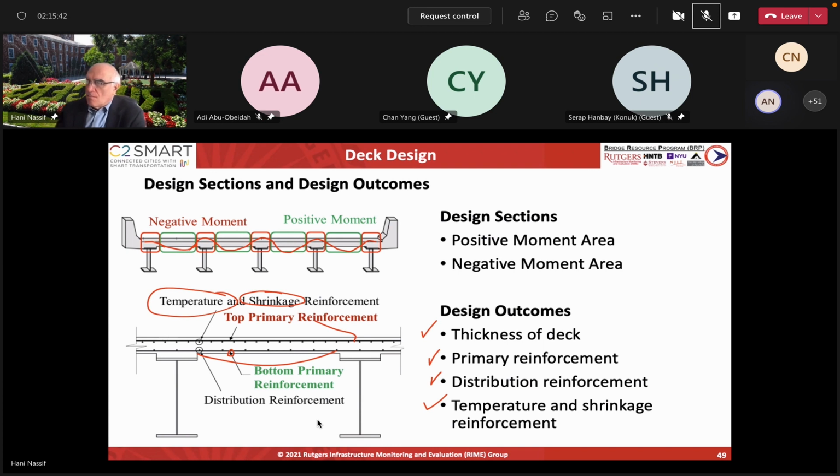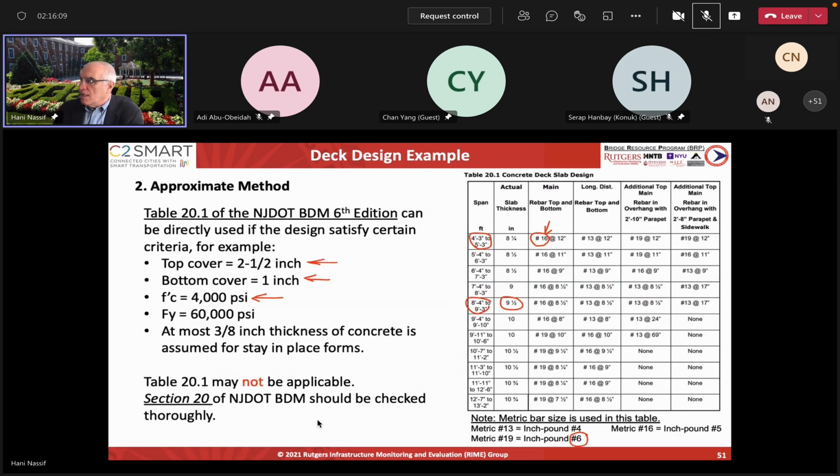the slab is like a continuous multi-span between the girders, and the negative region is mostly where the girders are. So not to use those. Well, we don't allow pinning into new decks anyway. Right. So that's something that people should be aware of. That's a good practical observation, Ali. Thank you. Okay. So let's go back.